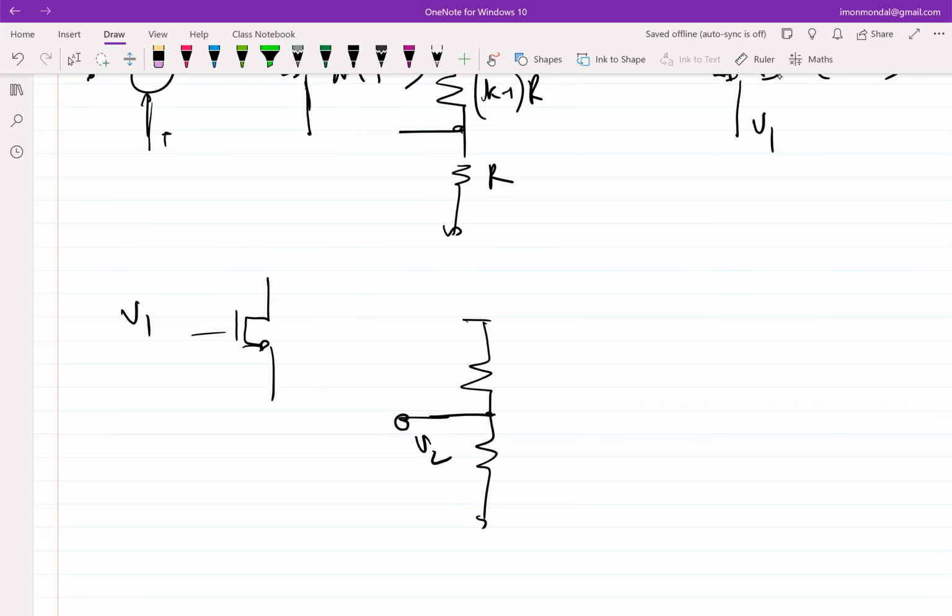Yeah, we can simply stick in a current source here, right? So this biases the transistor, no problem. We have done this till death, right? So source follower architecture or common gate or whatever you can name it. If I do this, the transistor will be biased properly and this node is available now. It's not ground. So if I'm able to connect these two, and assuming that no loading happens, then I'll be able to get approximately V2, right?